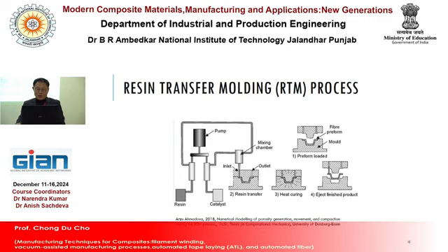Because the resin transfer molding process, as you see, needs the mold, upper mold and lower mold, both of those. So it can be used to manufacture small size parts only. It is not fit for large size structures.